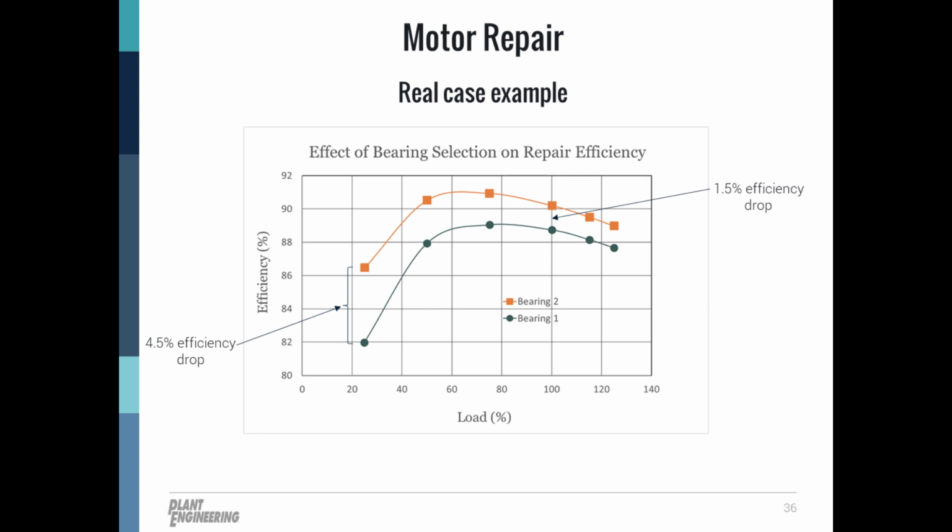top of the line motor bearings, proper greasing. Then the bluish green line below shows the efficiency results from testing when the motor was repaired with low quality bearings and under greased. You see a large gap between the efficiency performance of that same motor. So it's vital to make sure the repair vendor isn't making mistakes like this or using low quality components, trying to save money, cut costs, or else you'll then be losing money and electricity when you put a poorly repaired motor back in service.